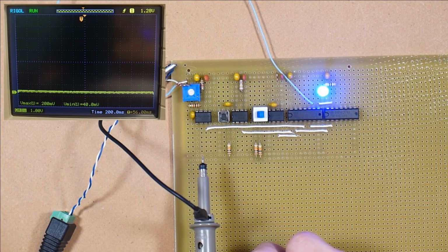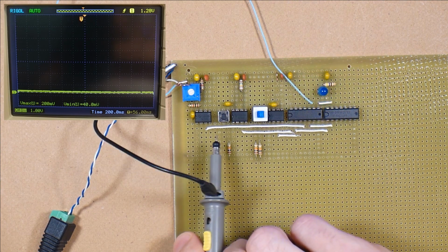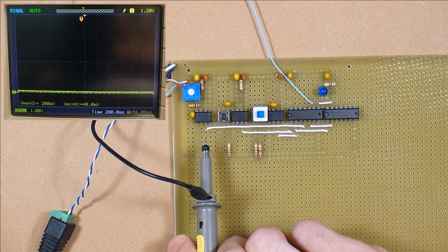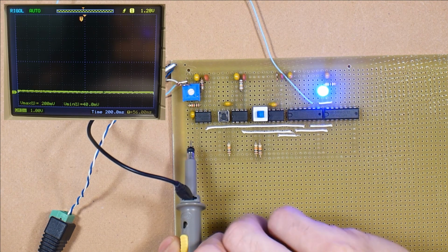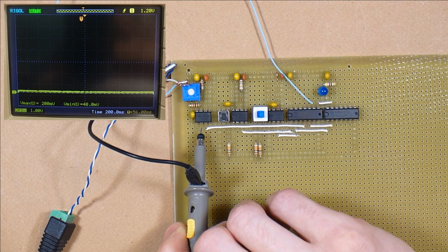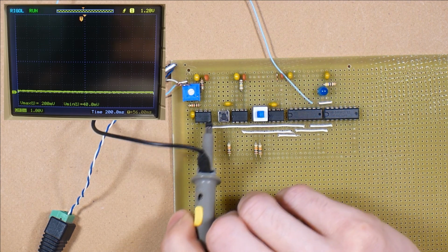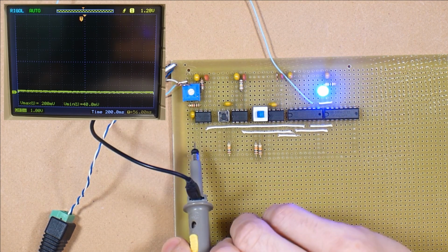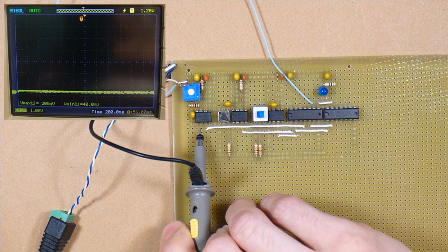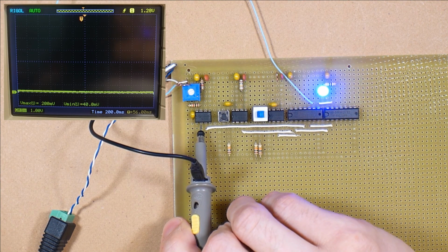So just for fun, we can measure the output of these timers in the oscilloscope to take a look at the output waveforms. If we measure pin 2 of this first timer, with the trigger, which is also connected with the threshold to the capacitor, we will see the curves of the capacitor charging and discharging.